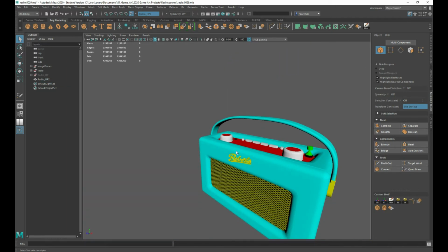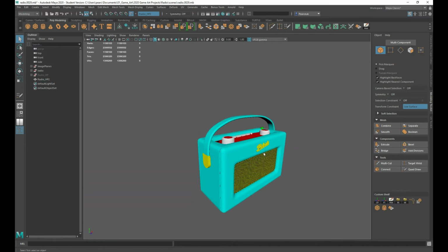So we've just gone over a couple of things where you can remodel it essentially from scratch by tracing it. You can use your quad draw where you literally draw on geometry. And then you can also use the sort of modeling tools where you're kind of tracing over it, but a little bit perhaps more loose. And then using the conform tool to kind of snap it in and combine that with the quad draw. So those sort of are the two potential methods.